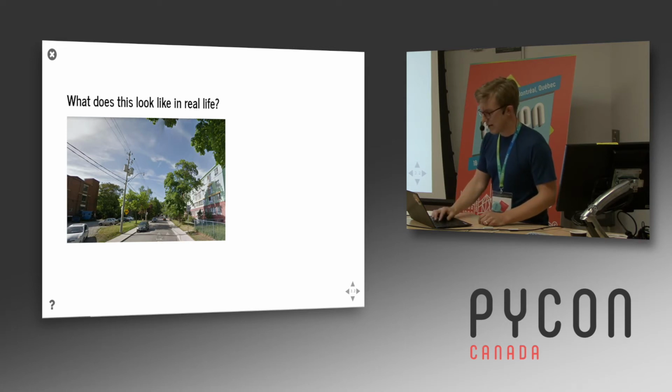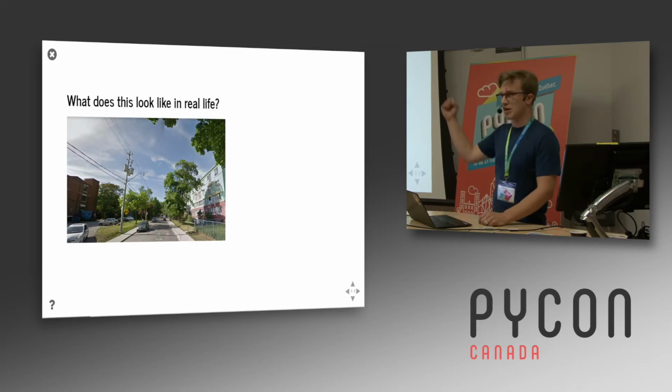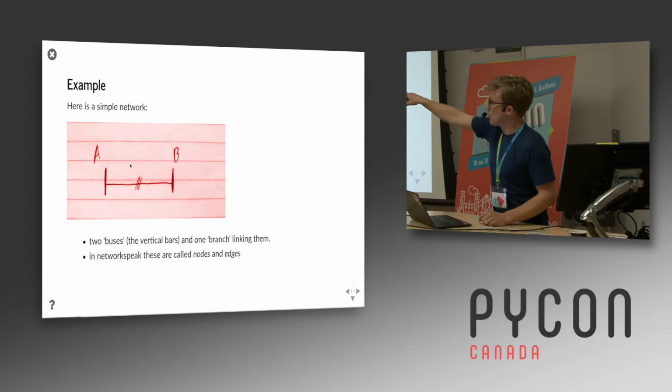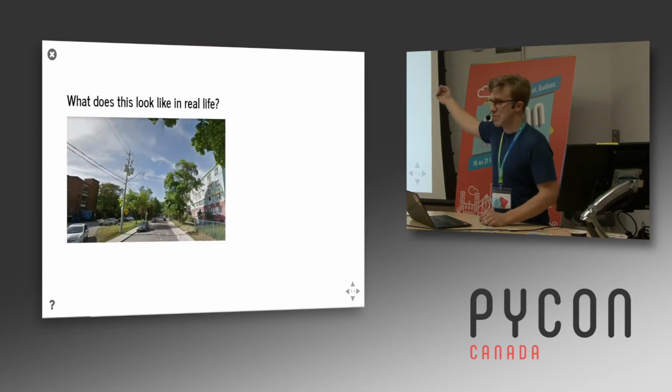So that's a line. And then in the middle, you see these 3 cylindrical cans. These are transformers. So this is what we would call a node. You have a line, 2 segments of line that meet here, and then you have a device tapping off. So that's a node, right? That's where we get our network topology. So you might think one of the nodes might be where those transformers are, and you have a line going off, and then somewhere else there's maybe another node.